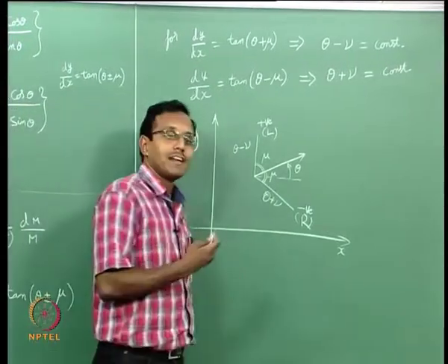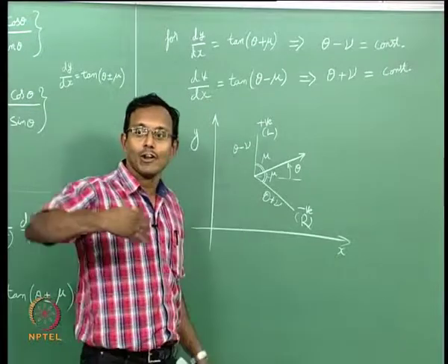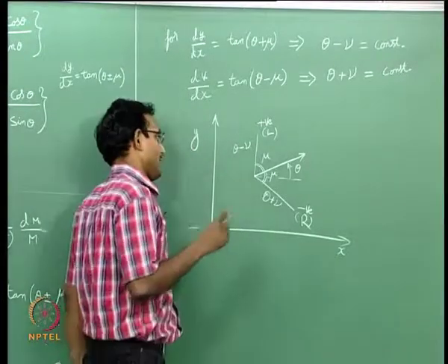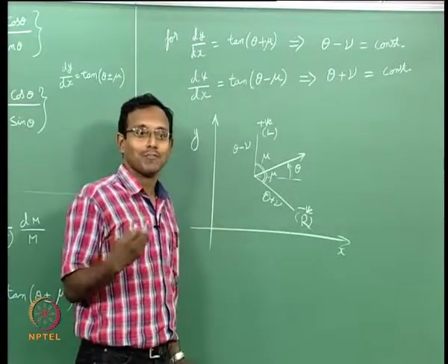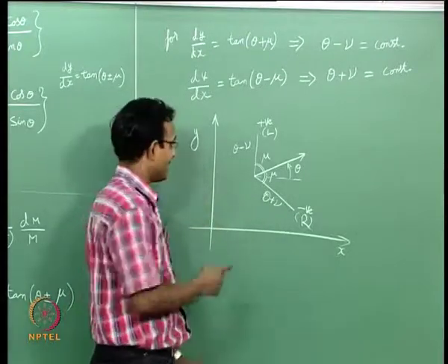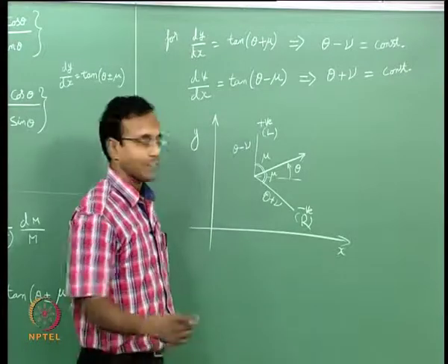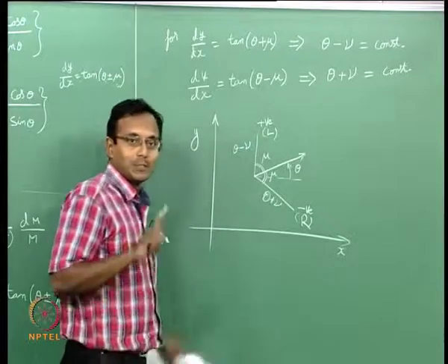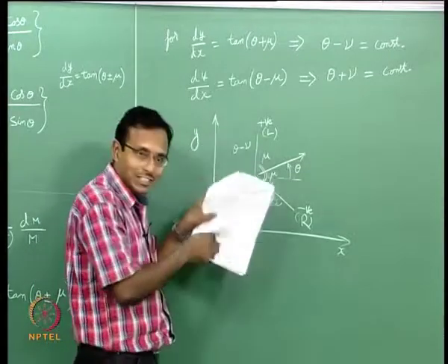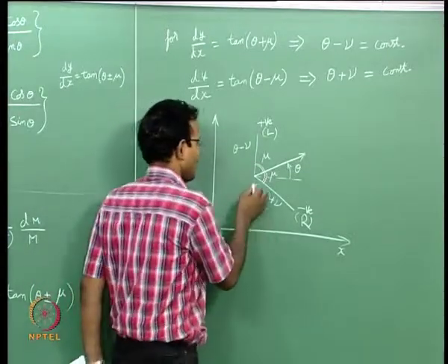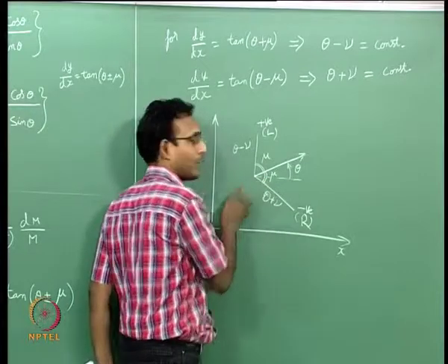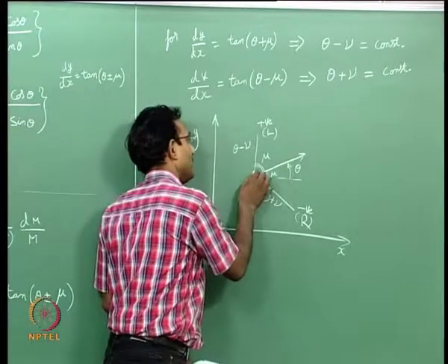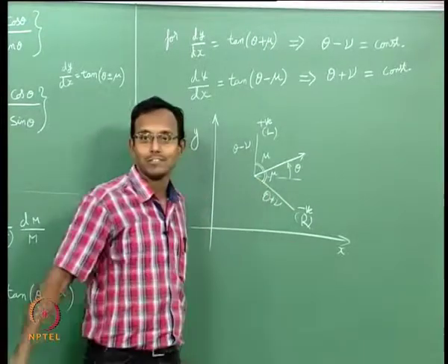So, what is the connection between this and our already existing understanding of gas dynamics? Now I have to give this connection of Mach cone and this. You have seen this picture before, where we are saying there is a fluid element that is going along this direction, there is a specific cone or a region inside which the flow will be having influence of this point, and that happens to be exactly this region.